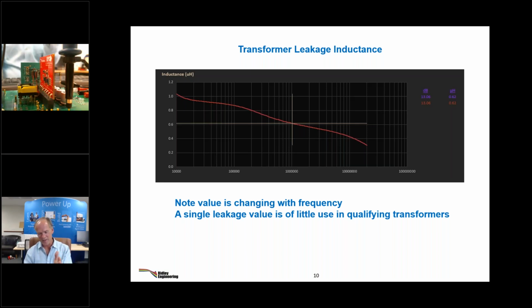I would try staying on this same core, and instead of 2 strands of secondary, I'd use 1 strand of 19, but I'd use a Litz wire for that one. So another variation there. I'd try another variation perhaps where I do the secondary first and then the primary afterwards. So you can try all the different permutations of making this transformer.